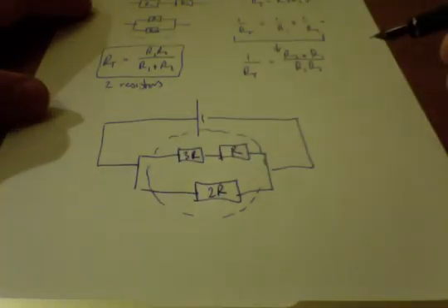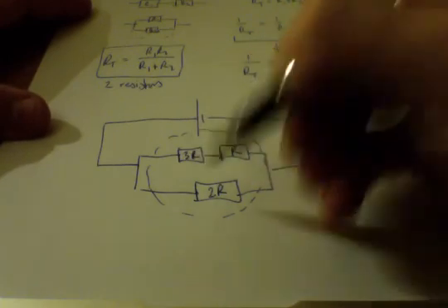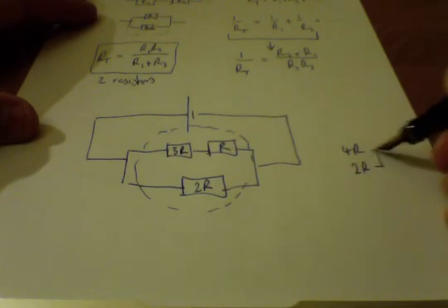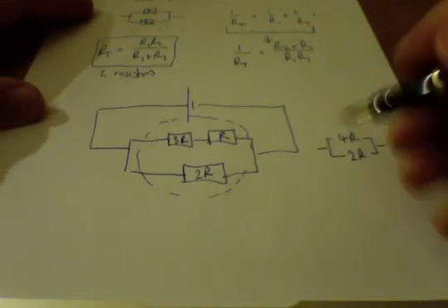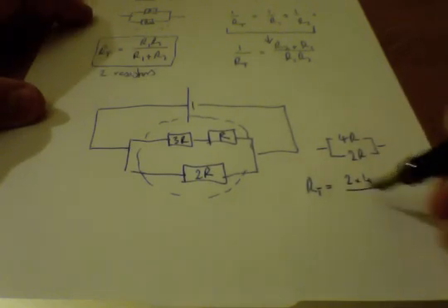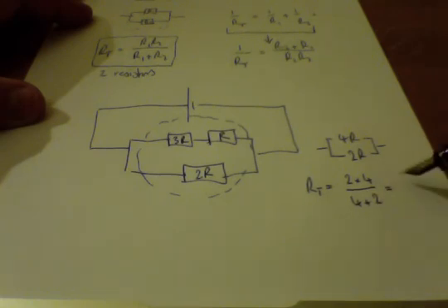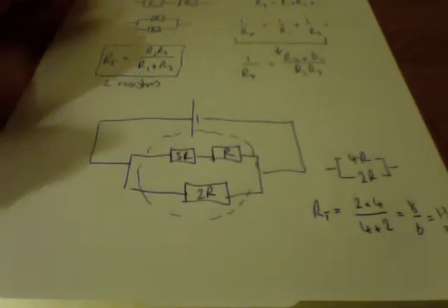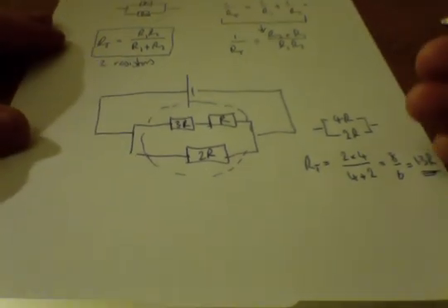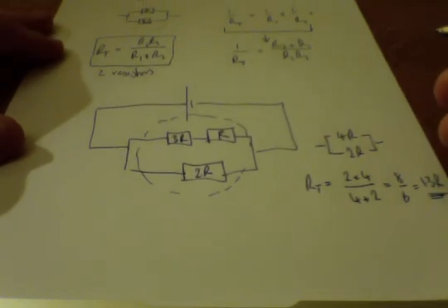What would it be? Well, we've got 2 in series and parallel, so let's combine those two. So in effect we have 4R in parallel with 2R. Now we can say to ourselves that the total resistance using the equation above is 2 times 4 over 4 plus 2, giving us 8 over 6, which is 4 over 3, 1.3 R. Really straightforward. And we can continue this complication all the way through. So I think, hopefully, that should be straightforward, those topic areas. Good, there it is.